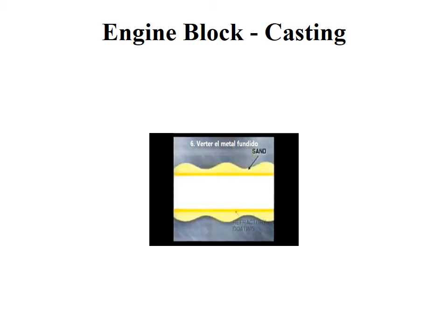As the liquid metal moves inside the coating, the heat energy causes the foam to liquefy, evaporate, and break down chemically. The temperature of the metal poured and the foam characteristics will determine how much liquid, vapor, and gas will be formed. Special coatings have now been developed for various types of castings, which have capillary action to absorb liquids, as well as permeability to allow passage of vapors and gases. Because there is nothing in the sand to burn out, creating collapse or mold wall movement, dimensions are very accurate.